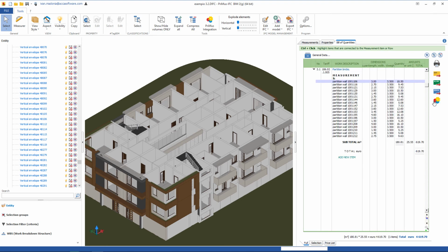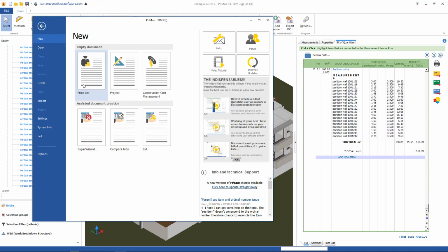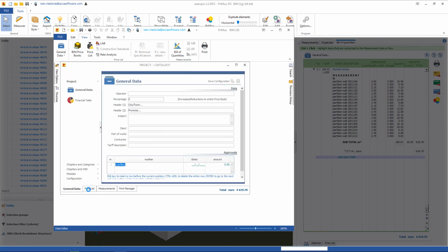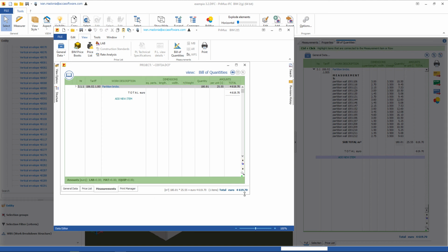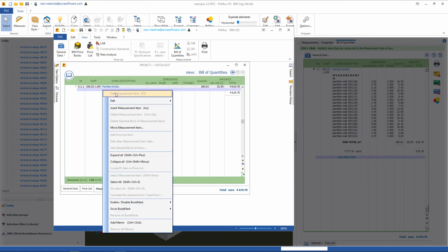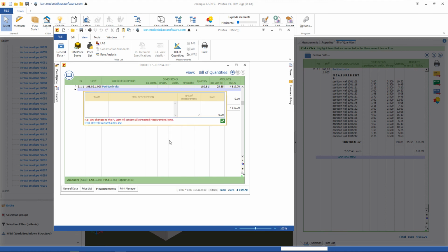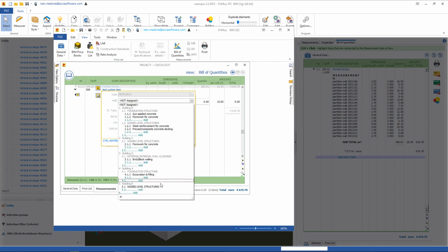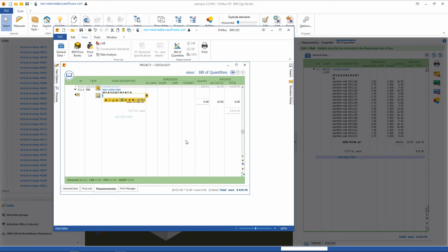Take advantage of the integration with Primus in order to use the professional version of Primus to integrate other BOQ data, measurements and quantities which are not detectable by the entities of the BIM model in the IFC format. In order to use the integration with Primus function, the Primus software must be installed. The integration process creates a dynamic connection between the two software to exchange the estimate and cost data information, processes, measurements, quantities, etc., coming from the entities of the BIM model in the IFC format.